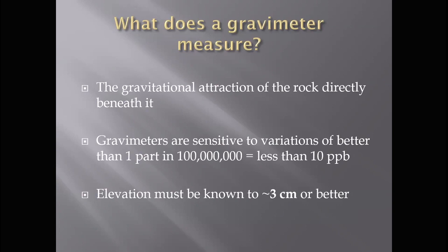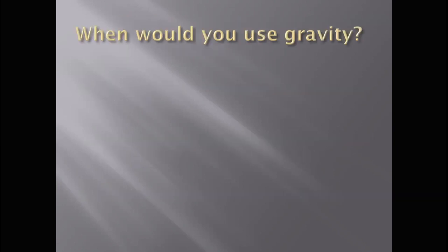And in order for this to work, we need to know our relative elevation or our exact elevation to 2 to 3 centimeters. So huge steps were made the day satellites started putting out accurate corrections to elevation. So we now use differential GPS radio. We use GPS as the theodolite, if you like, and we use a correction from a base station or the dumpy level. So essentially it's all done with GPS, which is another great technological advancement.